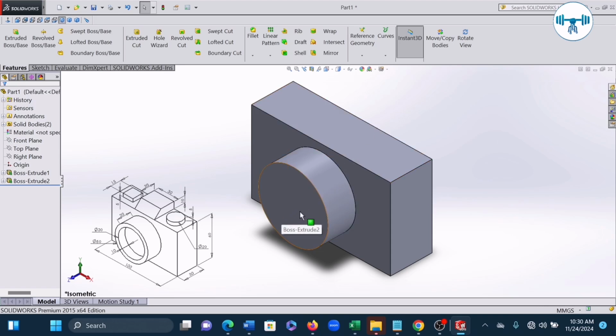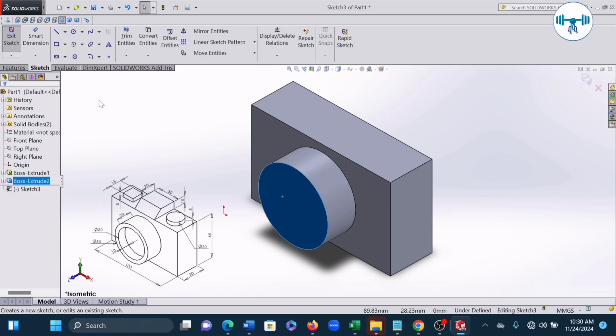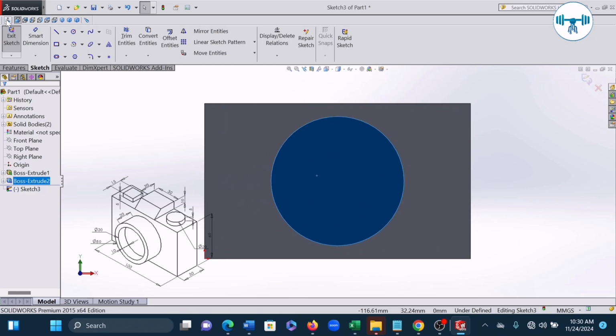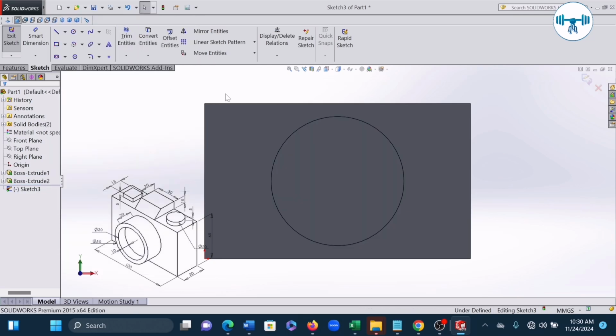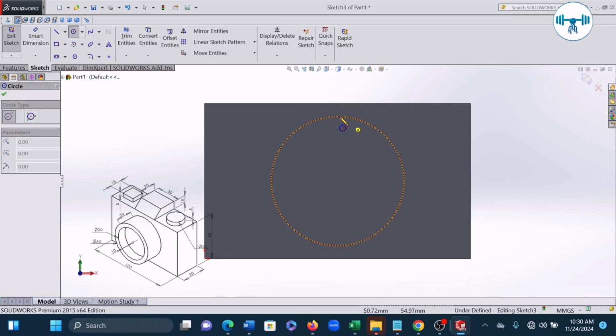On the face where we want to drill the hole. So on this face, can you see it? I'm going to click on this face and then I say sketch. Once I do that, I'm going to keep it normal to, so that I'll have better access to what I'm doing. Okay, now remember, I'm going to pick a circle. Remember, still from the center. So if I hover around the edge of this circle, I'm going to see the center.